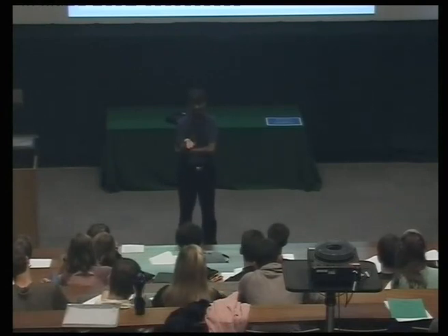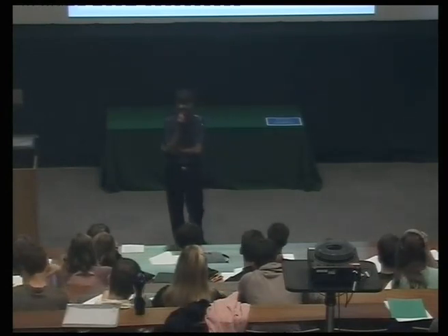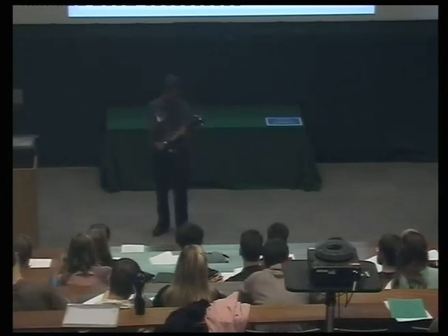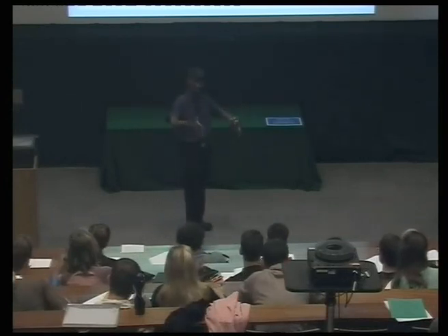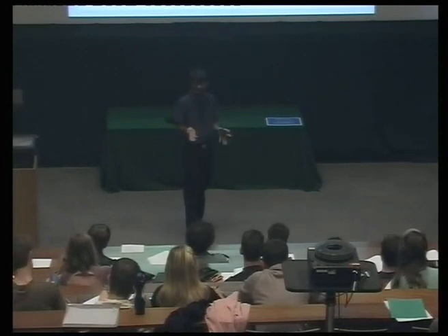Okay? Now, why in most solidification scenarios don't you need to have too large an undercooling to induce solidification? Heterogeneous nucleation. You're usually doing it in a container, and the walls of the container are very good nucleation sites. Okay? So delta T is going to be quite small, and therefore this approximation is reasonable.